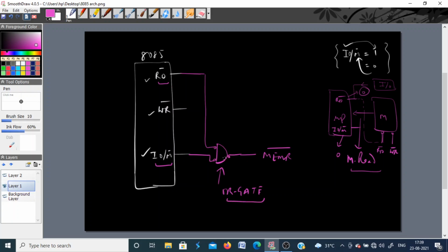Of course, this is represented in the digital circuits in the form of inverted NAND gates. So if this input is X, this is Y, and this is Z, what is Z in this case? It is X bar, Y bar, whole bar. Because the input is already inverted, we have an inverter here. So it is X plus Y, nothing else. This is just a notation that is used in the book. Otherwise, you can simply use an OR gate here also. No issue.